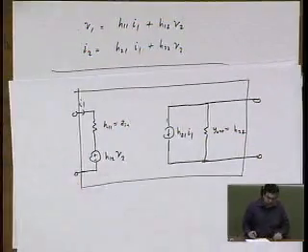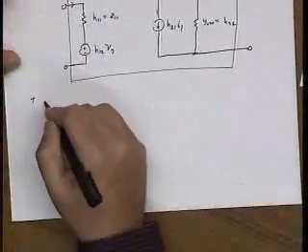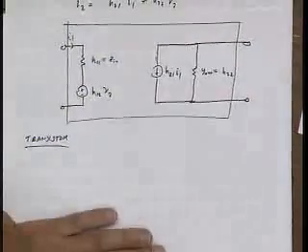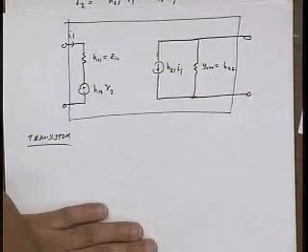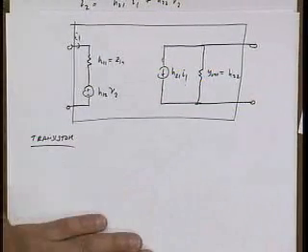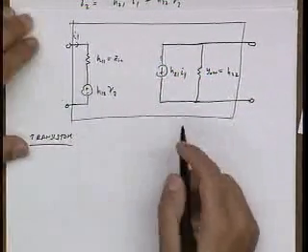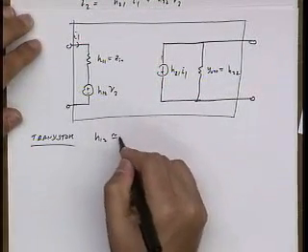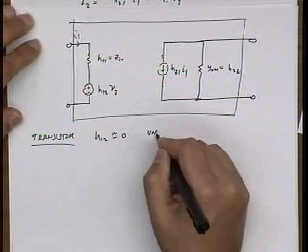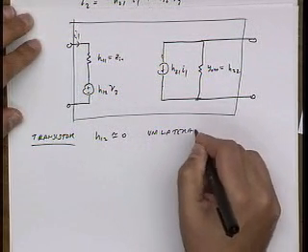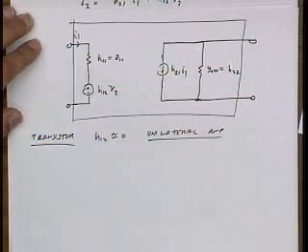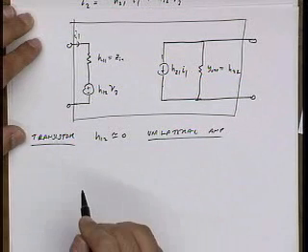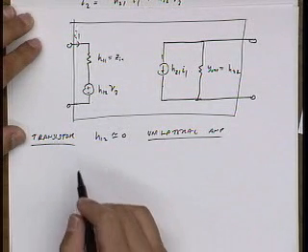Okay, well, let's calculate the H parameters of a transistor. In fact, it shouldn't be very hard, right? Because we kind of called our most beloved model the hybrid pi model. So, well, again, I'm not going to bore you guys, so let's do the simple case. Let's assume H12 is equal to 0. So this means it's a unilateral amplifier. And again, you can go home and do the more complicated case. I know you guys have nothing better to do at home, so okay.